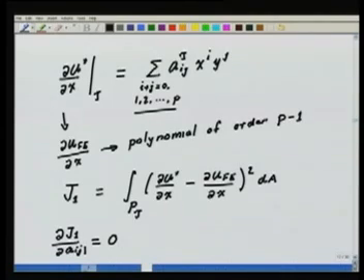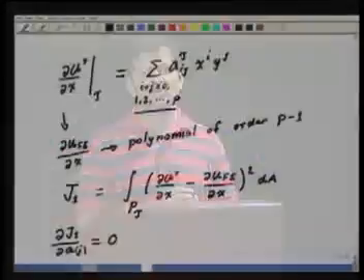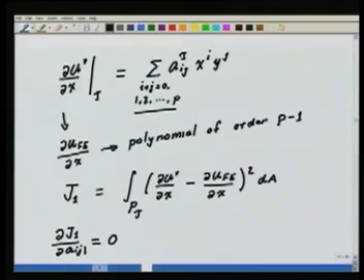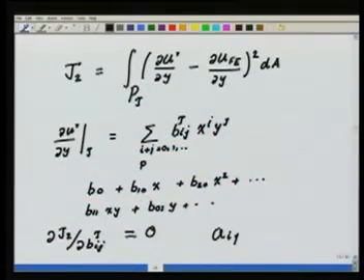Solve these two at the element level, and this is going to be a very small problem. The size of it is going to be simply (p+1)(p+2)/2 for each element. Okay. So these small problems can be easily solved, and I will obtain the set of coefficients a_ij for the element τ, b_ij for the element τ.